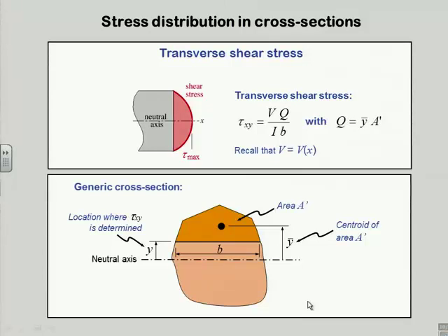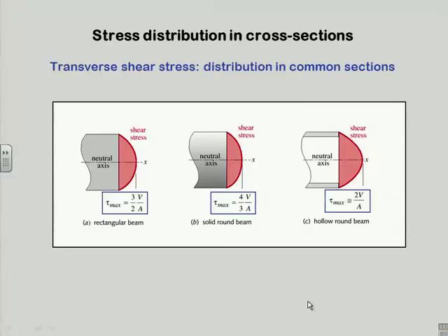So again, the shear is distributed in some fashion across this shape, and obviously the geometric shape is going to make a big difference in that function, right? Because the Y bar is going to change and the area is going to change and such. But as it happens, we usually have one or another fairly common cross-section in a beam. It's probably rectangular, or it's an I-beam, or it's round. And so these formulas have been calculated for those common shapes, and they're in a table which we can easily access. I don't show the I-beam here, but it's in a table in the book.